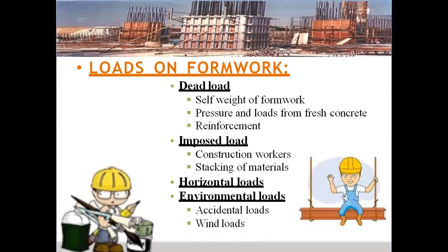The loads on formwork. What are the different types of loads which are placed on the formwork? They are dead load, imposed load, horizontal loads, and environmental loads. The dead load includes the self weight of the formwork, the pressure and loads from fresh fluid concrete, and the reinforcement which is provided for slab designs.